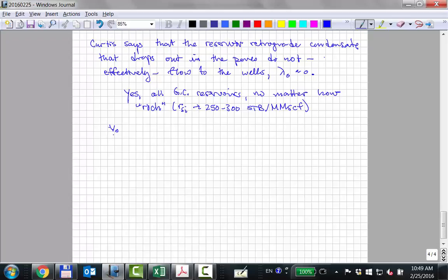Right. So the maximum oil volume over the oil plus gas volume from the CVD test, which is basically the oil volume over the initial volume at the initial saturation pressure, okay? The max value of this is around 45%, okay? For this very rich fluid.